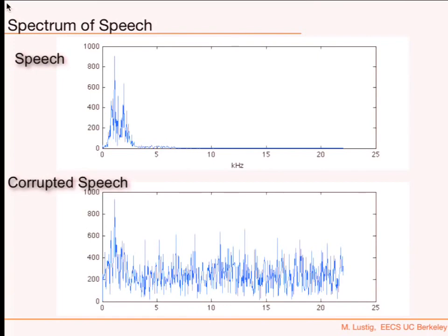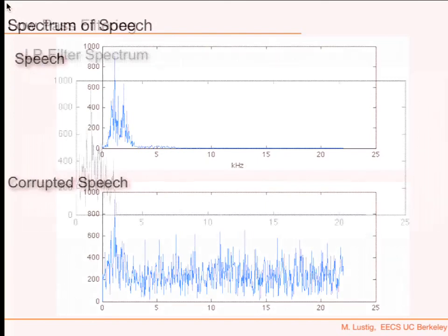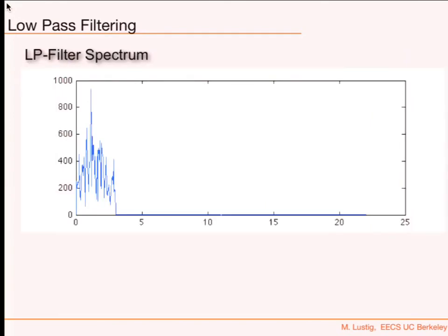So we could reduce the shot noise by filtering a lot of it out, right? And that will be a linear operation, just bandpass or low-pass filtering, right? So after we do this, here is an example. So we filter. Let's try to hear.